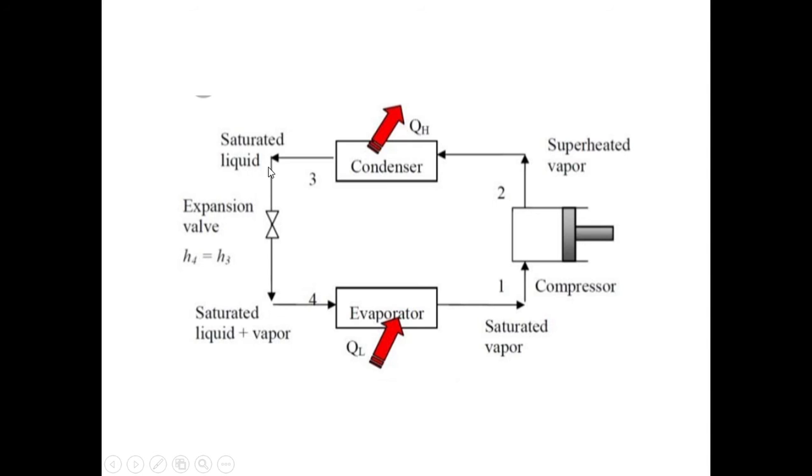That saturated liquid enters into the expansion valve where it flashes, so its temperature reduces and pressure also reduces. So this lower pressure, lower temperature liquid refrigerant enters into the evaporator coil where it sucks its latent heat from the space to be cooled and gets vaporized. This vapor refrigerant enters into the compressor for the next cycle and the same cycle repeats.